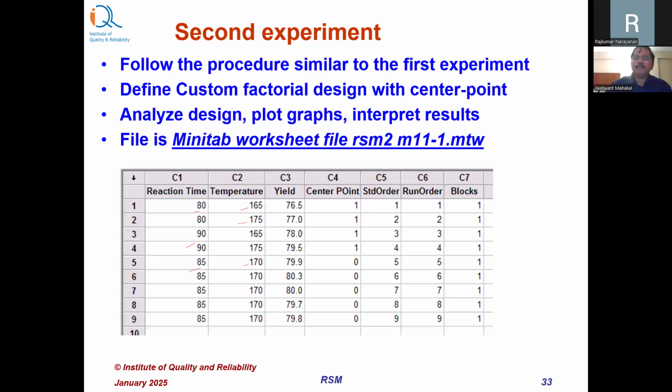Sir, I have one question. We are manufacturing liquid silicone rubber molding machines, where we have a curing time of, for example, 90 minutes, and we have to reduce the curing time. The three input factors are pressure, flow, and temperature. With respect to that, I am using the surface optimizer there. Yes, you can use that.